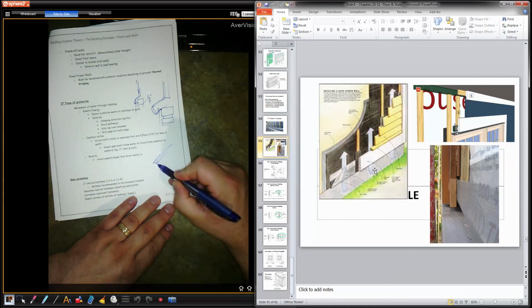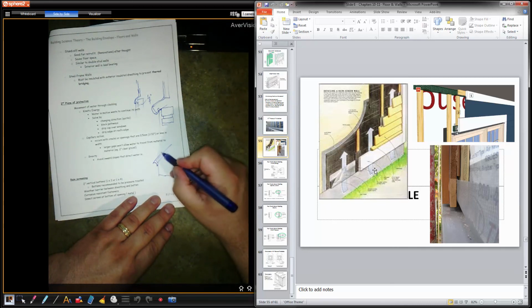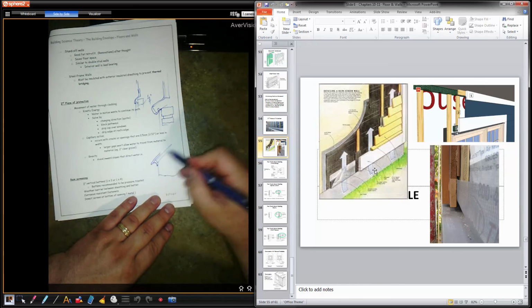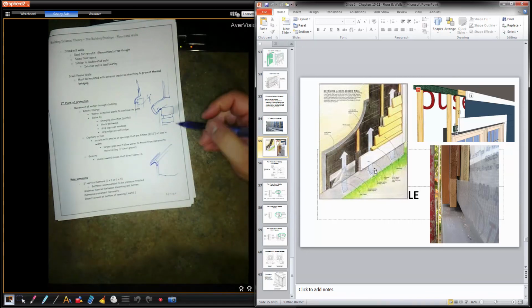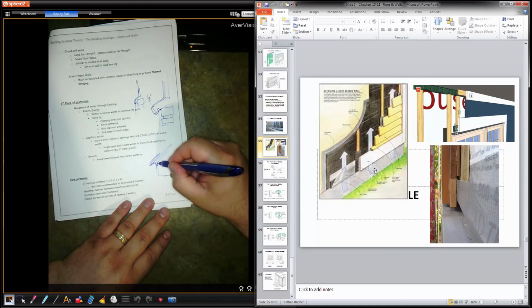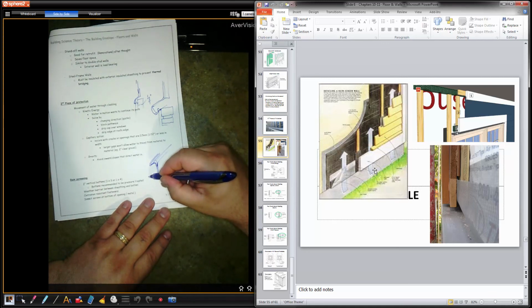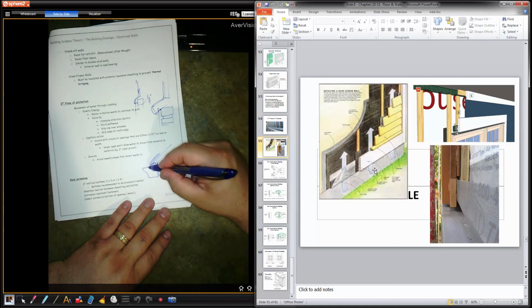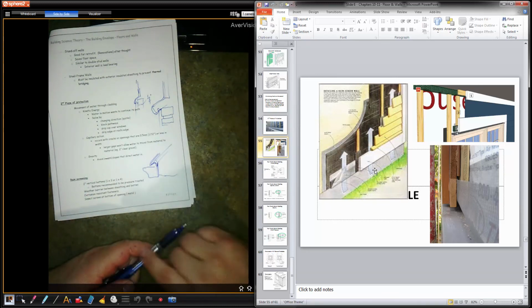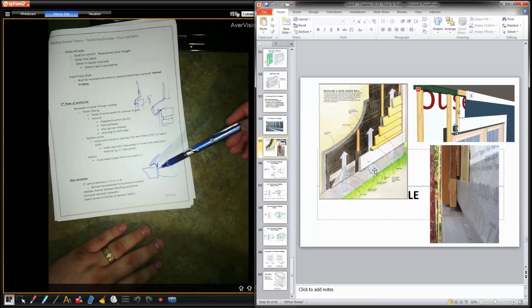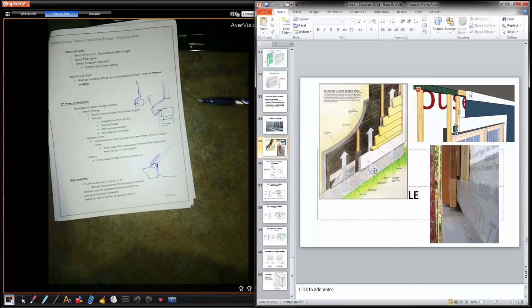Kind of goes like that, curls around, out a bit, and there's your fascia board. Again, you got your shingles that go a little bit further, 1/2 inch, 3/8 past. The water will follow, get to that point, and then drip. Usually into eavestroughs. So eavestroughs will slip behind that drip edge, curl out like that. The water drips into the eavestroughs and gets the water away from the foundation. Okay. So kinetic energy on a window, on the drip cap, or on a roof. It's water in motion that's going to continue its path.